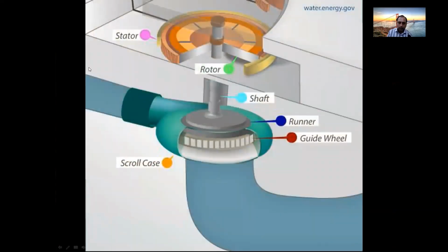So this is a typical layout or drawing, I would say, a diagram. Here is the pressure shaft which is meeting. Generally here you have an inlet valve. It is called the main inlet valve. It's a butterfly valve. And then there is a spiral case, or scroll case. The purpose of that scroll case is to evenly distribute the water to the turbine. That goes to the turbine. Then water goes from the turbine to the draft tube and goes out.